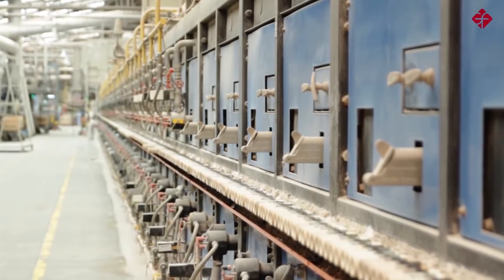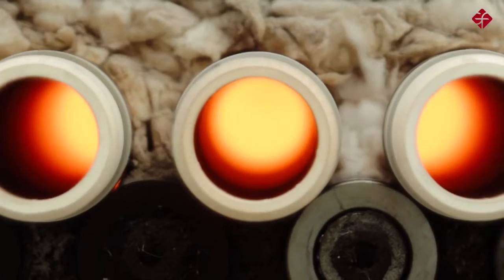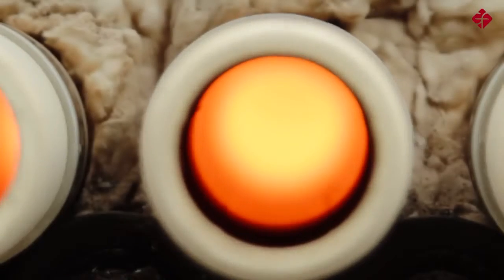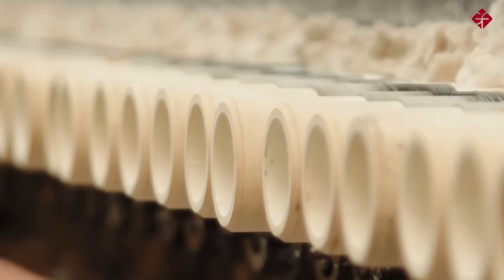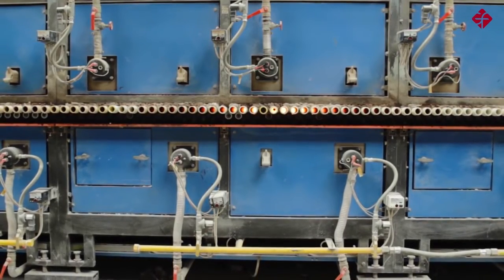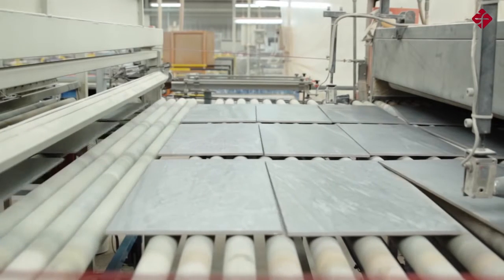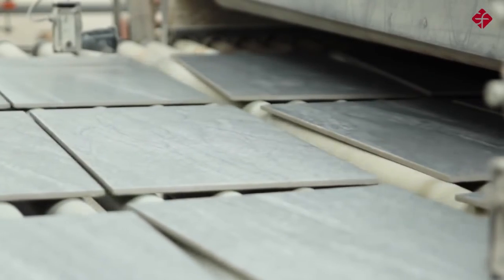They reach a maximum temperature of somewhere between 1100 and 1200 degrees centigrade. The flame is in direct contact with the tiles being fired. The process is highly optimized in terms of heat recovery in order to reduce fuel consumption, and the kilns are designed in such a way that the hot gases produced are reused to preheat the tiles in the first firing stages. In this type of kiln, it is very easy to produce a large quantity of material in a very short time.